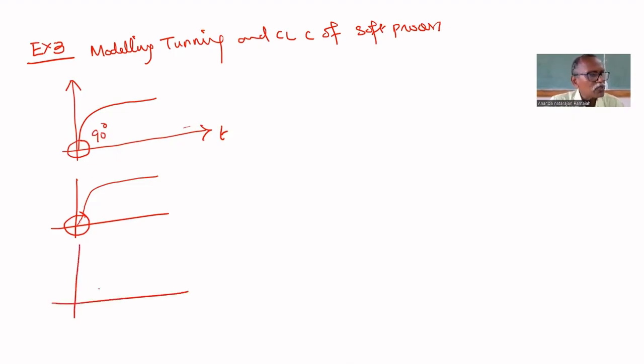As order increases, suppose order is fourth order, it will be like this. That's why in the level process, you got S curve. This is called S curve, reaction. As order increases, you will get S curve. The dead time will come into picture. Initially, there is no response for some time as order increases.